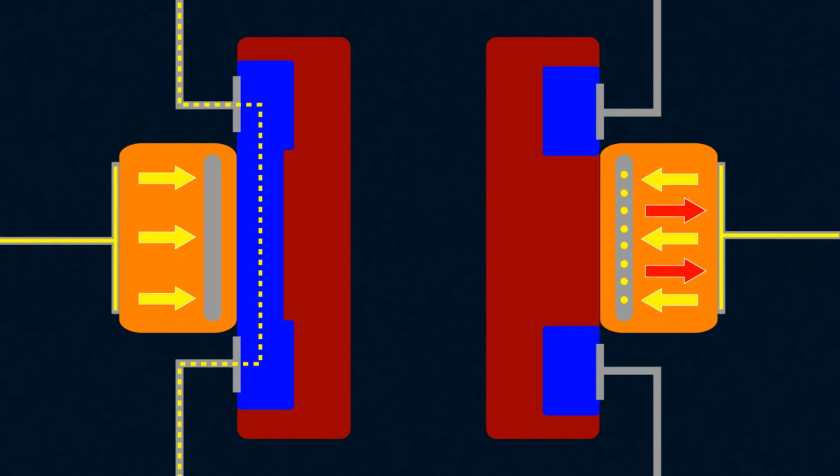So our device will operate differently depending on whether there are electrons in the intermediate conductor. If they are present, the transistor will remain closed even at the voltage that would open it if they weren't there. Thus, by placing and removing electrons from the gap between the gate and the semiconductor, we can change the state of the system. If there are no electrons, the current will flow at the working voltage on the main gate. And we say that a 1 is written in the cell.